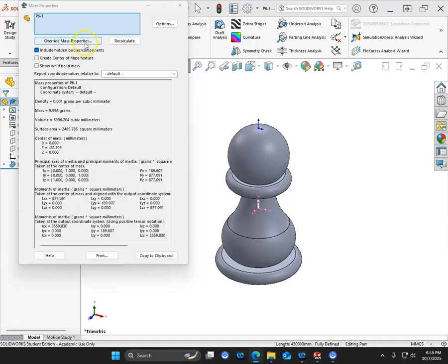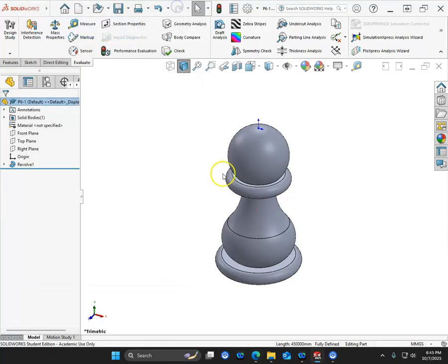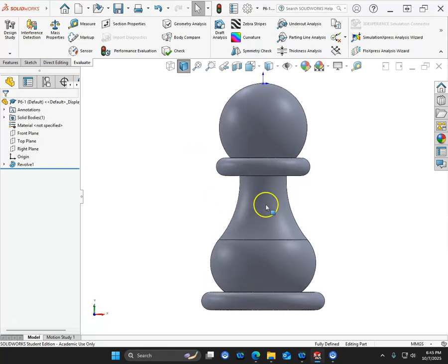So as revolve, as we get into these, and we start kind of feeling out this geometry, going through the process, there are tricks and traps just like there are in the Boss Extrude, the patterns, everything else we've done up to this point, except now, thinking of the manufacturing of this, I always just look at this as this is going to be a turn. This is going to be on a lathe to build the part.